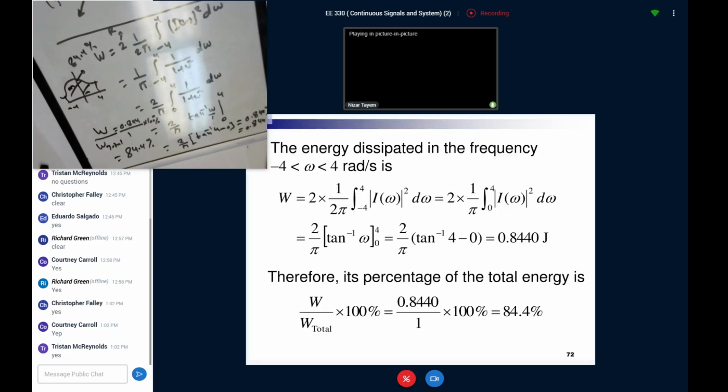So it's very important to use Parseval's theorem to find the essential bandwidth required to send the signal, because in some examples, they might give you the percentage, and we need to find what omega is in this case. We can do the same thing here. If I know the energy, for example, if I need 95% of the energy to exist in this band, find the bandwidth that contains 95% of the energy. Anybody tell me how we can do that?